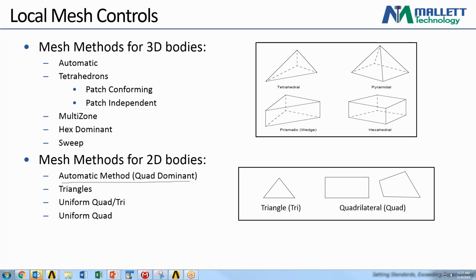And generally, right, we treat contact pressures, really any contact result, similar to a stress concentration. If you're truly trying to get an accurate answer, you have to run a mesh convergence study, right? You should be able to refine that mesh continually until you see the pressure, or generally looking at pressure or friction force, whatever criteria you're looking at, should converge to a value. So if it's not done converging, that may be what you're seeing, where you're seeing concentrated contact pressure on nodes.